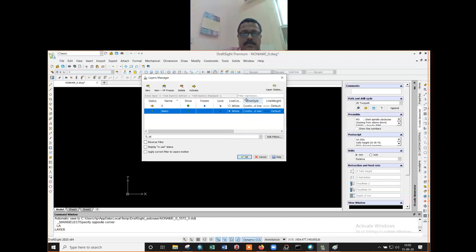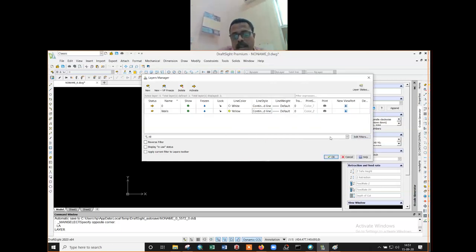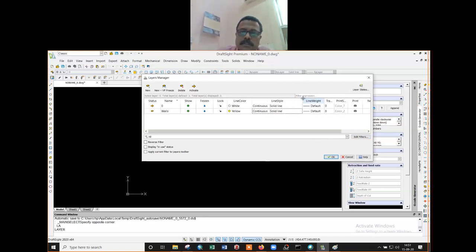So suppose I want to choose a different color for the layer, maybe it is in red color or yellow color, and then I can include some line type or the line style. So what may be the different kinds of lines that you can choose? So there are different line types which you can choose for the layer. By default, this is the solid line. Okay, so normally whatever we draw for the walls and the interior stuff, most of them are actually solid lines.